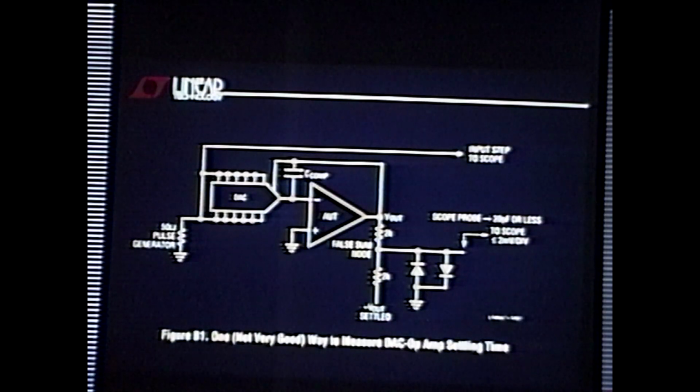One of the most difficult measurements to make is the settling time measurement, which is to say, you hit an amplifier with a hard, fast, clean step, and you want to know how soon it settles within some specified error band and remains there. So it's got to slew and ring about the final settling point and finally stay down. And the problem with that, of course, is the amplifier typically will slew volts. The standard test has always been 10, and then settle down within a millivolt or less. And the name of the game is, how in the name of God do you observe that settling time? Because you're asking the instrumentation to settle out to very, very small fractions of the total step.